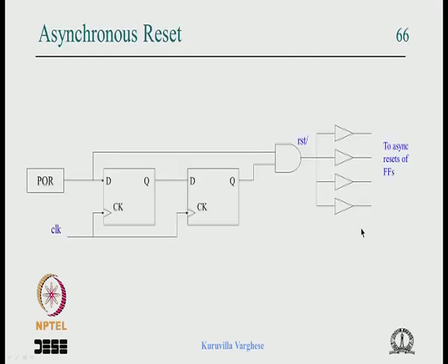So essentially what we have looked at in the last few slides is the reset recovery time, which is related to metastability. This is related to the asynchronous reset of a flip flop.